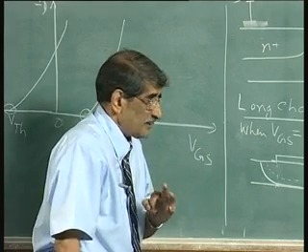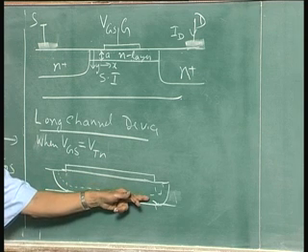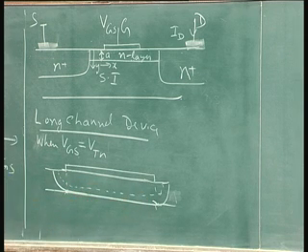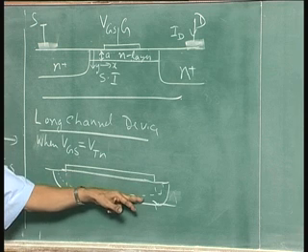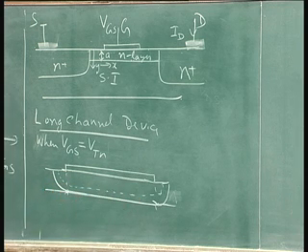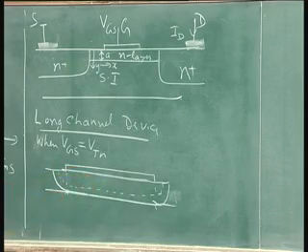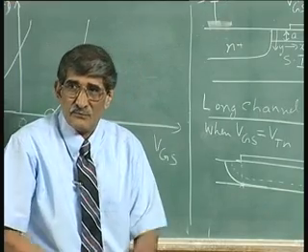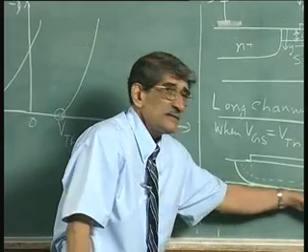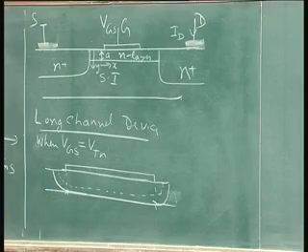So, what you are telling now is, if I move along this line from the source end to the drain end, there is no potential variation. If you move at the edge of this depletion layer, there is no potential variation. Please understand this very carefully. Okay. If there is no potential variation, that is where we take that current is 0. If there were potential variation, current would have been there if some charge is there. But when you go to the edge of the depletion layer, what is the charge concentration? We take it as 0.